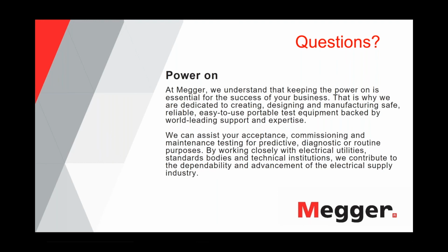to offer here, because you can measure leakage current. Now, in leakage current, you have a similar issue because the leakage in paper is higher than the leakage in XLPE. However, what you can do in these cables, and that's how it's done, is take the composition of this feeder or this cable, run a VLF test including the leakage current, and fingerprint it. You say, okay, now I know in this configuration, this cable has so much leakage current.